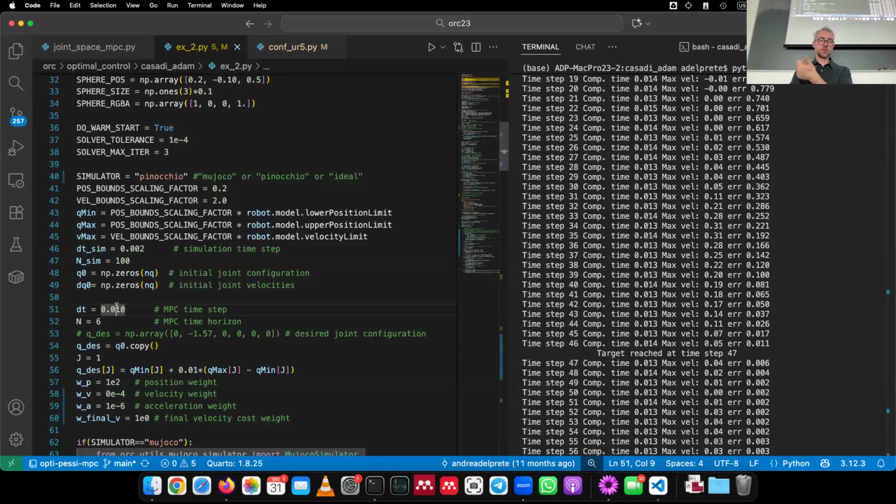Yeah, first of all, actually, I would say this is the second point, but since you got it first, the second point is that you only ensure constraints at time steps. So the further apart the time steps are, the more likely there are constraint violations in between them, which is something that we observed last time when working with the unicycle doing collision avoidance.